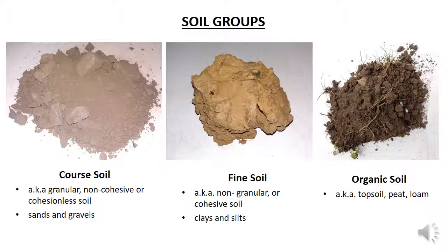Fine soils are silts and clays. They may be referred to as non-granular or cohesive soils. Fine soils are usually the result of mechanical, chemical, and biological weathering, so the soil properties usually vary significantly from those of the parent rock. The chemical weathering, in particular, changes the soil particle properties, so there is an attractive force between soil particles. This attractive force is called cohesion. The strength of a fine soil is derived from both the cohesion and the friction between the soil particles. The properties of fine soils are mainly related to their water content.